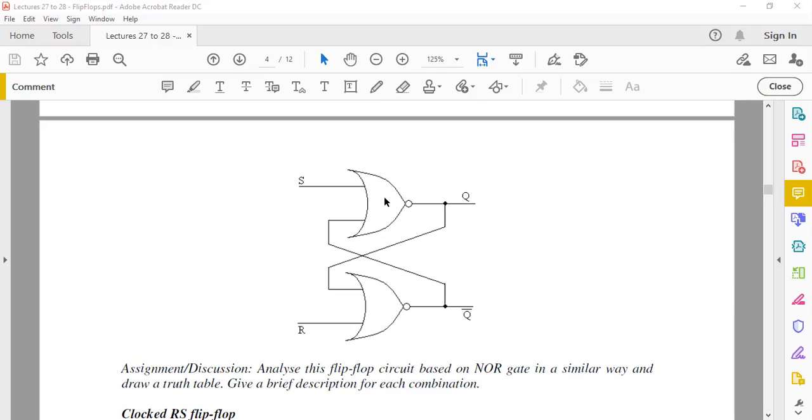You see they have to change state and become different, and then from this point onwards you can make your S become high now and see what happens, and make your R become high now in turn and see what happens. Then you can understand whether it is actually an active low signal or active high signal. The indeterminate state, like we say, is when S and R are both high, because it's trying to produce Q and Q bar both low. So study the circuit now like we've done earlier in detail, and then we're going to look at this back in the tutorial class.